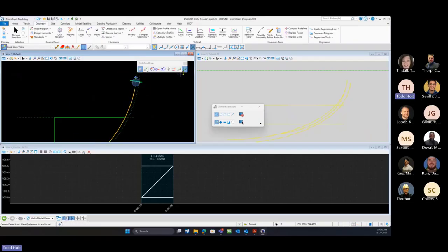And with that delta station favorite, I'm going to hit O for origin. I'm going to select my curve back top as my reference. And then I want to do my intersection snap. And I'm going to do the intersection of my curve back top and my sidewalk front.